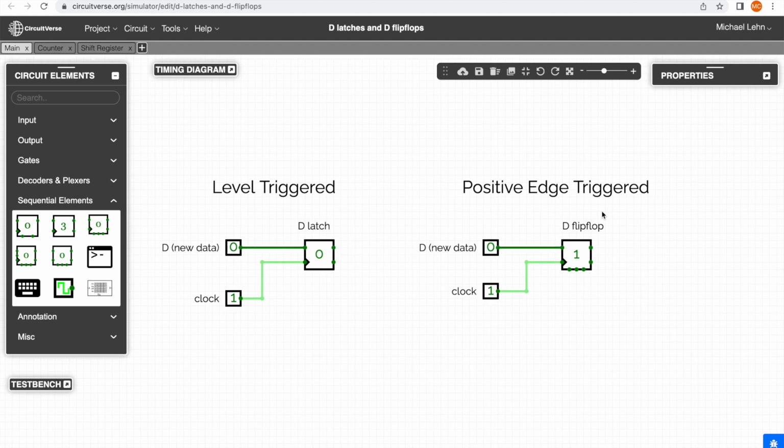Now I also want to give you an idea how a D flip-flop can be built by using two D latches. The reason for that is that the mathematical simplified description of a D latch is very simple. You can use truth tables, or you can use a simple logical equation. That means if we have this understanding of how a D flip-flop is built on top of D latches, we can, in a simplified mathematical model, describe how this D flip-flop behaves.